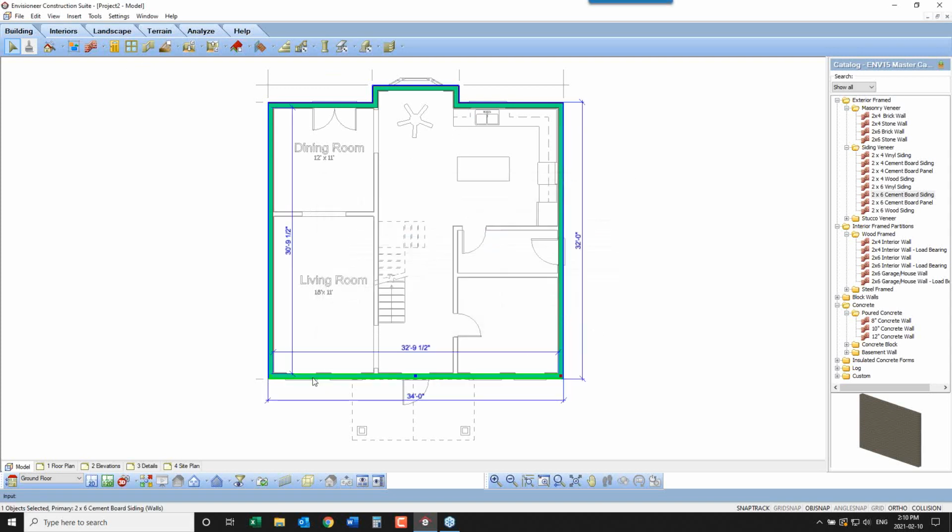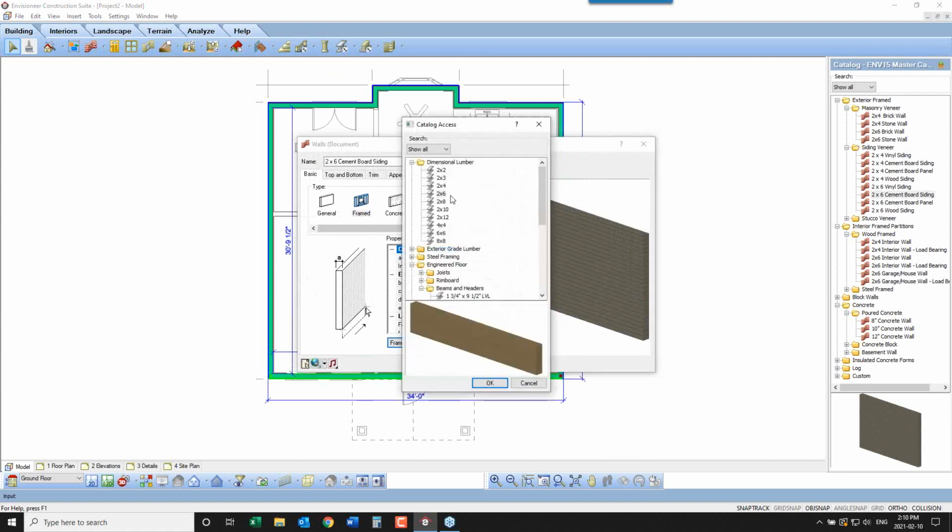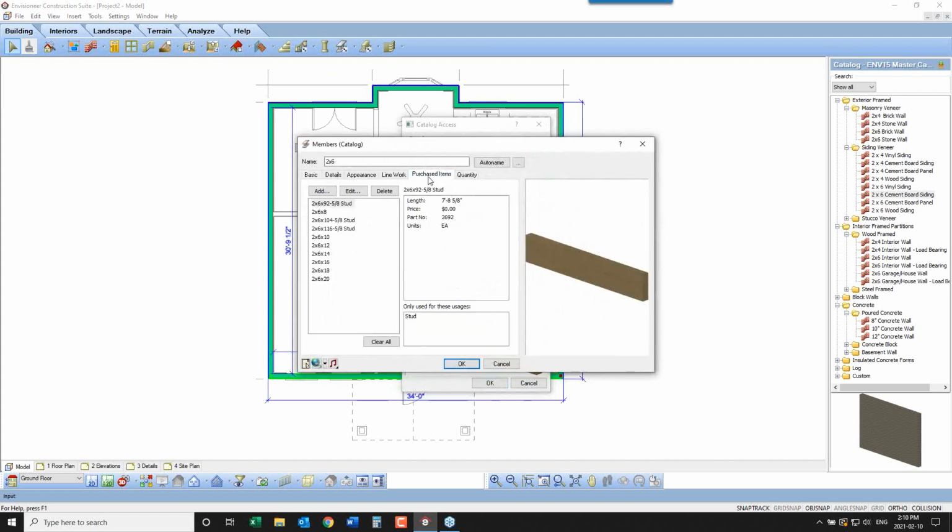By looking at this wall, right-click, look at its properties, I can see all the information that it's assembling. It knows to frame this wall and use a 2x6. And just by putting in that 2x6, that 2x6 has information behind it as well. It stores all of the purchase lengths that are available for that 2x6. So there's that 92 5/8 pre-cut stud length. It grabbed it when it was looking at the studs. It said, I will use you, you're the right length. If it was a 9-foot wall, it would have come down to the next pre-cut stud length and used it.